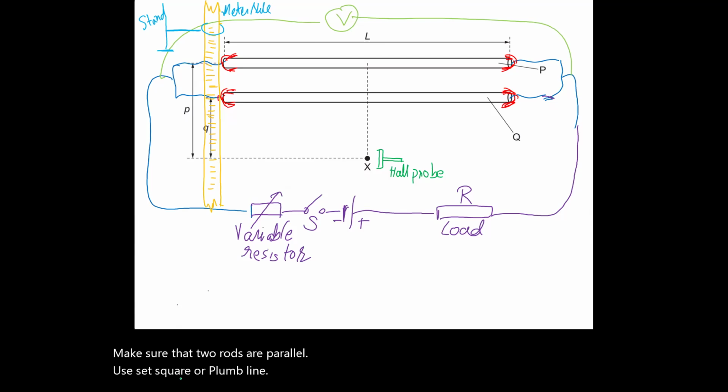Variable resistor should be connected in series with resistance at its maximum.